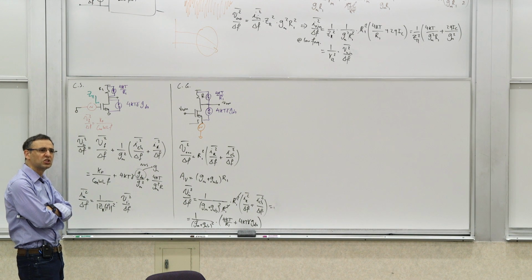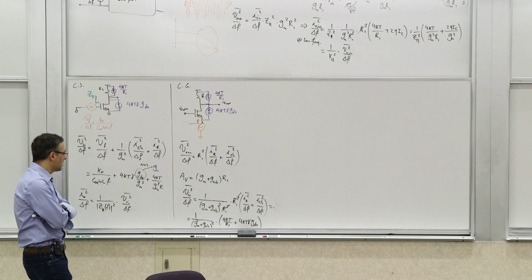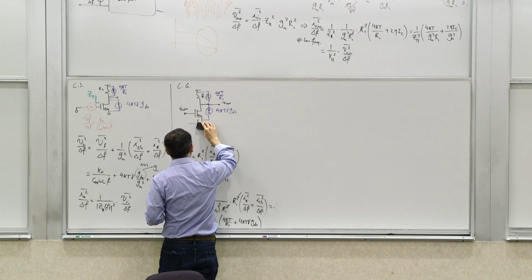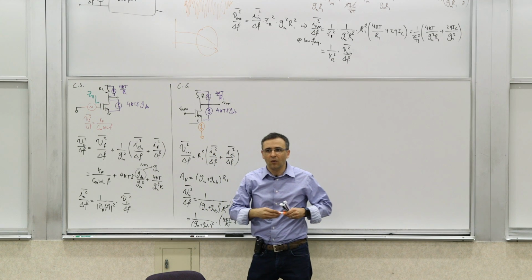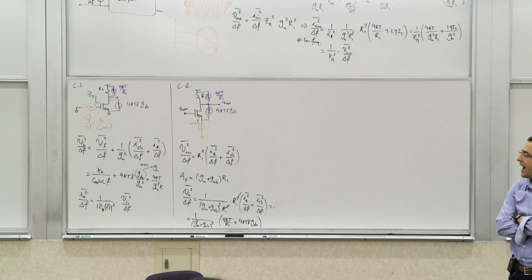How about the input referred current noise? You need to calculate that too. In that case, that's a current source sitting in parallel with the input, which would be like this. Now, let me ask you a question. What is the output noise? Is it the same or different?